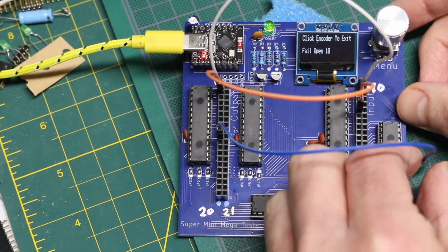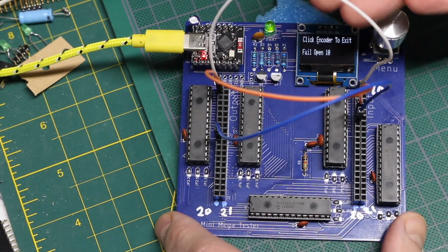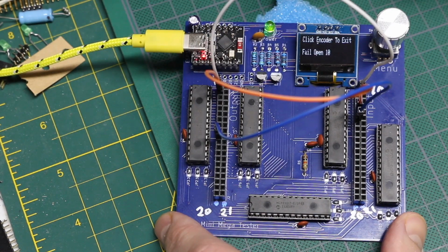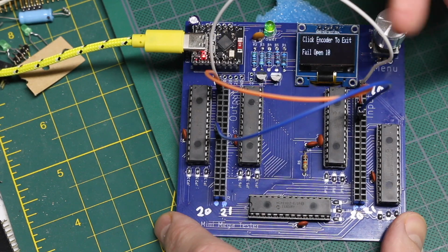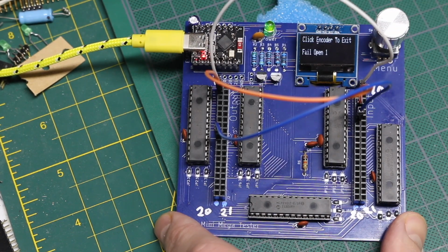and also put pin 10 somewhere it's not supposed to go, if I run this again, I should get a fail open on pins 1 and 10 and a short or miswired on 1 and 10. So it's open 1 and 10 and then short 1 and 10.